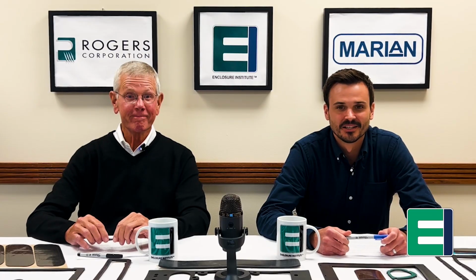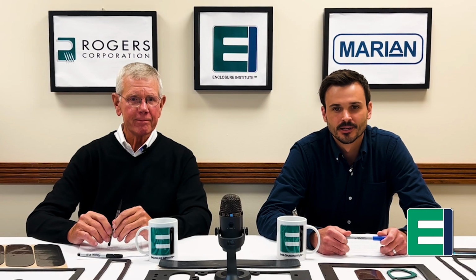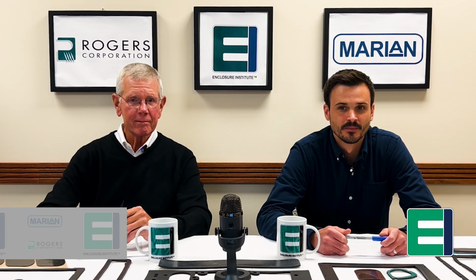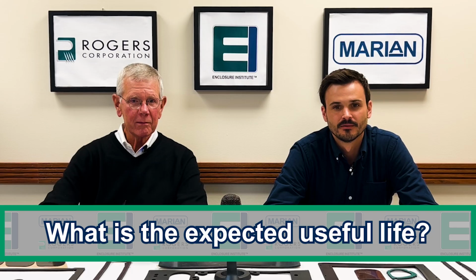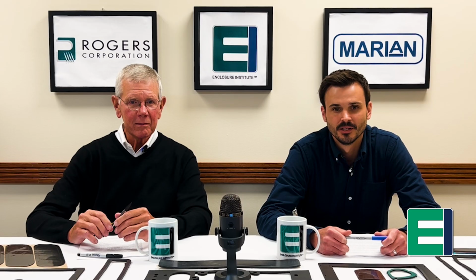But polymer degradation most often takes time. It doesn't happen overnight. So maybe the first question to ask yourself or your team is, what is the expected useful life of the device that you're trying to seal? Making the distinction between short-term, long-term, or something in between will help you decide whether polymer degradation is worth concern.